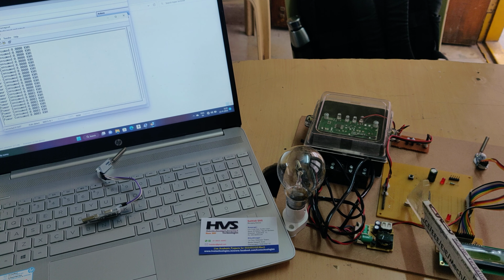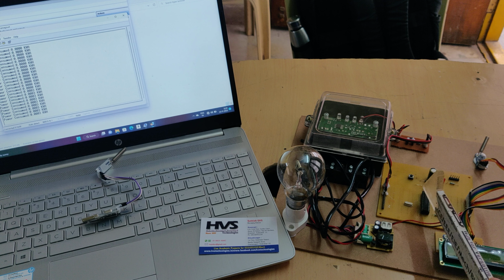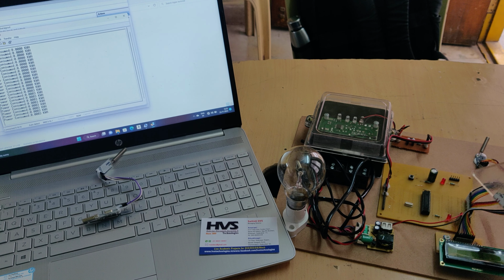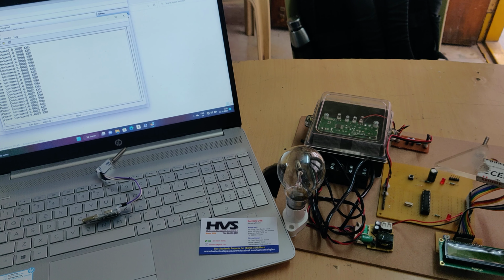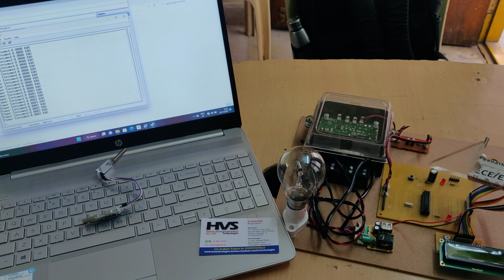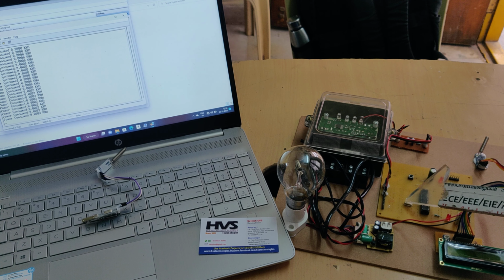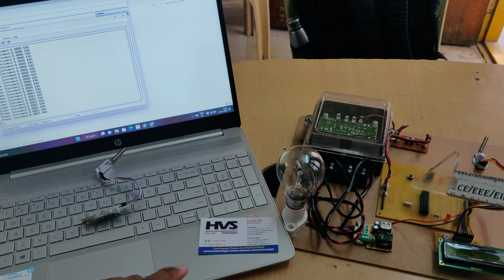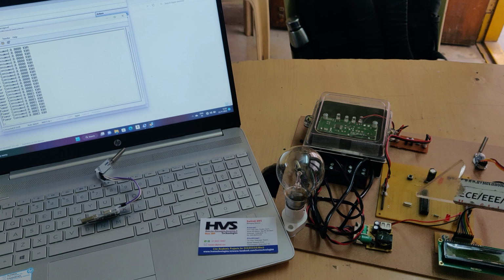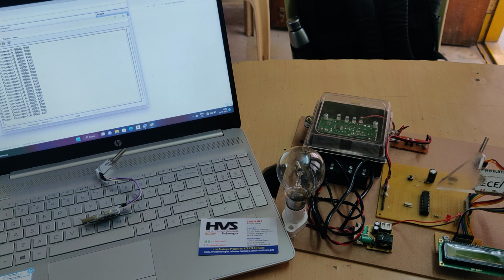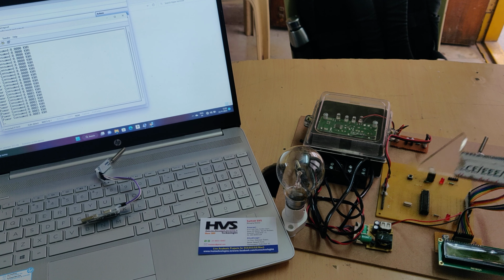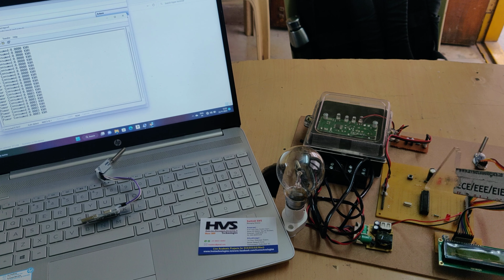The main purpose of this oscillation frequency is that we have provided the set of instructions in embedded C language to read the data, send the data, and display the data. These instructions will be executed based on the clock pulse from this crystal oscillator. Per instruction the controller needs 1 pulse. So we are providing 20 megahertz of clock frequency to the controller, so that the controller can execute 20 mega instructions per second. That is the speed of our controller.